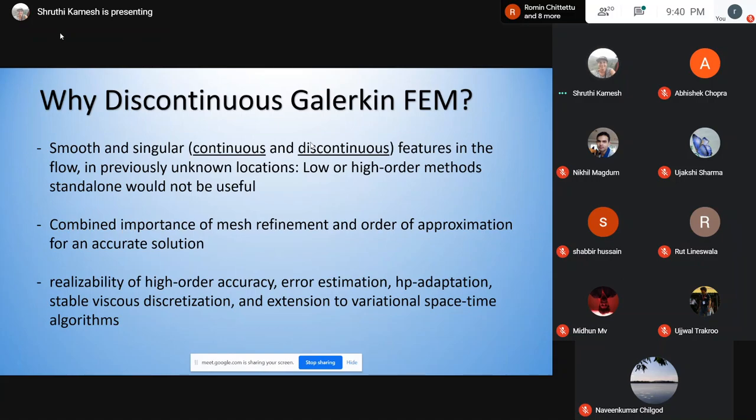discontinuities in a flow, but you don't want them to be too discontinuous. That is, you want to smooth it out and see how the particular shock or phenomenon happens. You want to know how it leads up to that, and that's why you use viscous discretization, right, to resolve that particular discontinuity.